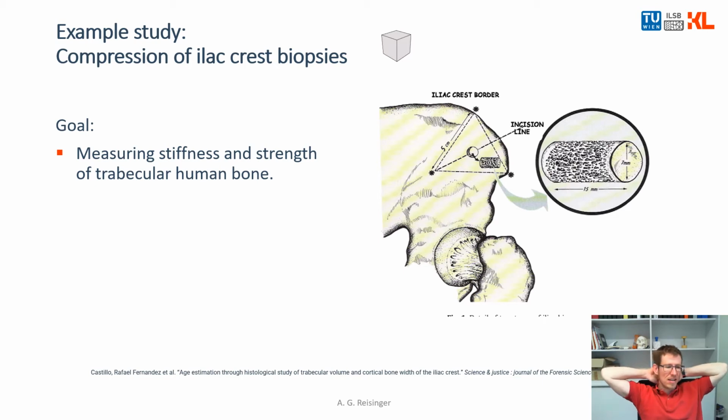This is done by controlling the stress and strain state in the material, and simplifying it so that many stress and strain components are 0, and only a very limited number, or only one number in your stress vector, not necessarily the strain vector, is unequal to 0, has some number, and the number is known.